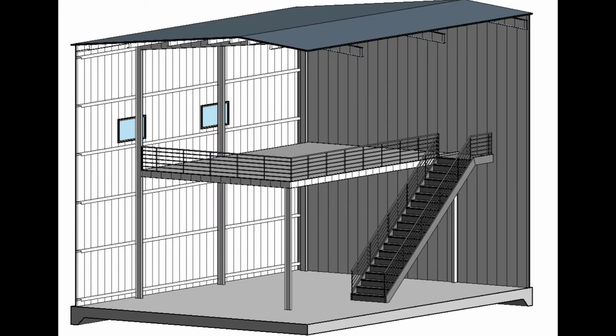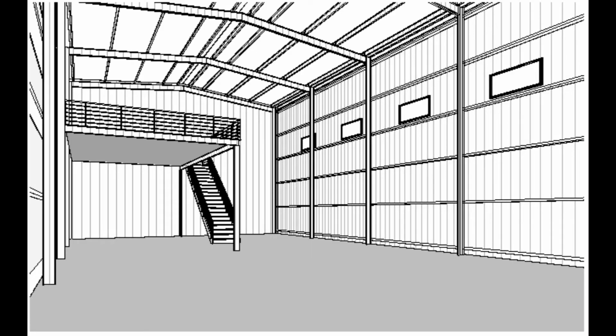As for the mezzanine, we modelled in an 11.1 metre by 6.6 metre mezzanine, exceeding the minimum requirements as per the brief, and a 254 by 102 UB column and beams at 22 kilograms per metre, supporting this. The design intent was to assume joists spaced out to support the floor.